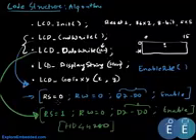So these are basic commands and how the LCD uses them. Now the only difference for the 4-bit mode is the commands that we set to initialize the LCD. As we will discuss, in the function set, instead of setting it as 8-bit, it would be 4-bit. We'll go through the code at the end. Before that, we'll see what the difference would be for the 4-bit mode.